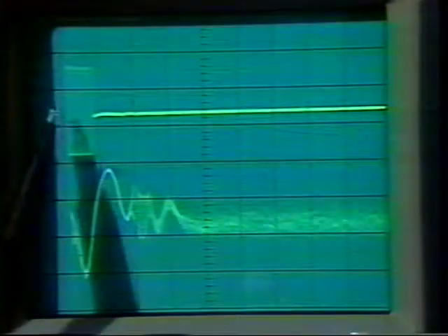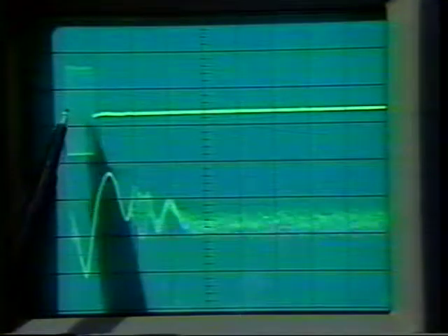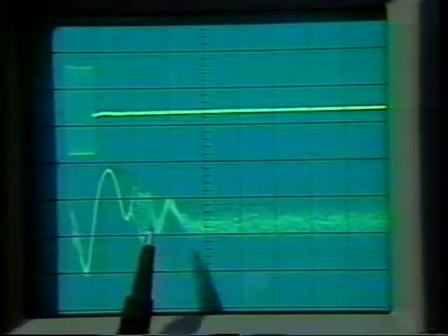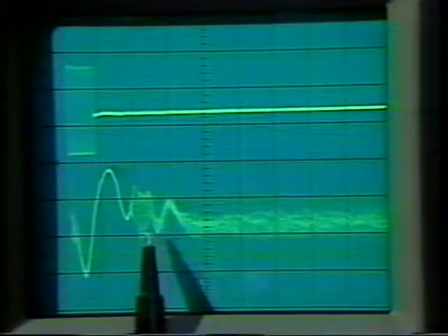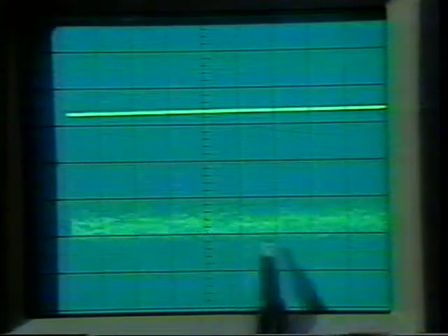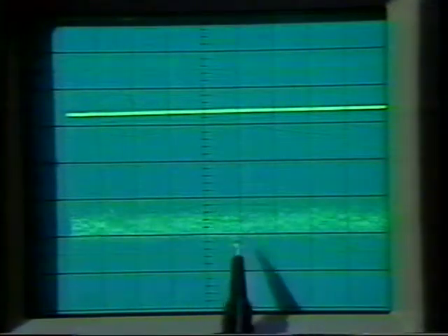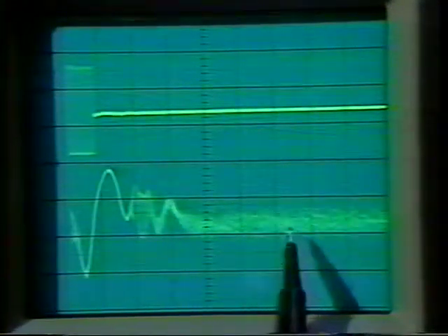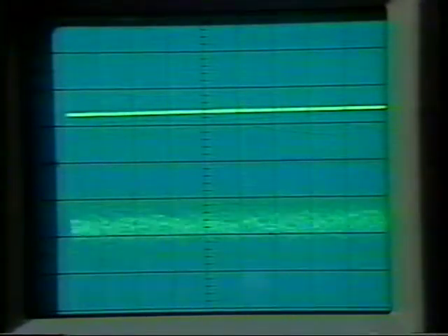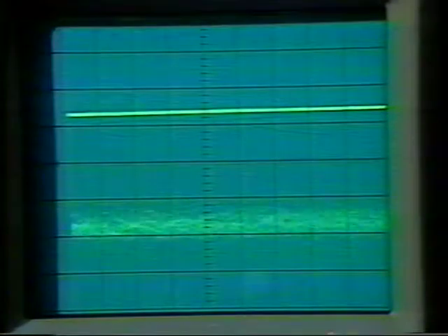This is the transmitted pulse that comes out from the transmitter into the antennas. We receive this signal back from the antennas into the receiver. We start sampling the data in this area here and get good results in this noise level out here. The atmospheric echo is actually contained in the noise level here. By long-term averaging on the order of minutes, we can extract the atmospheric echo and tell what the winds are.